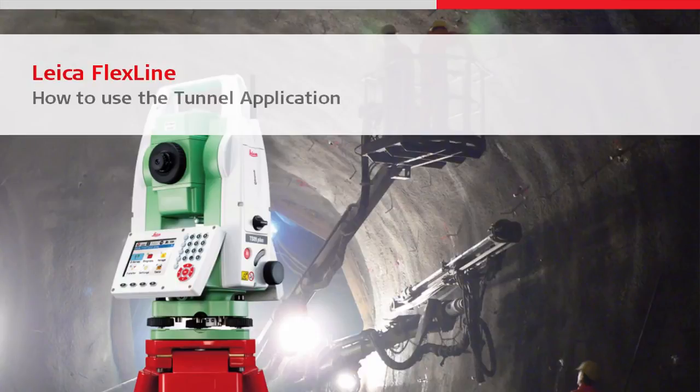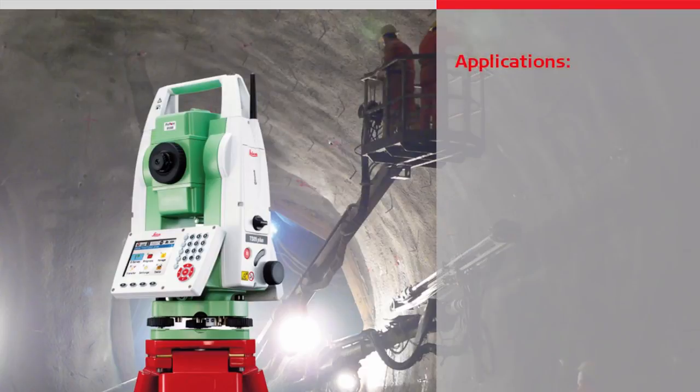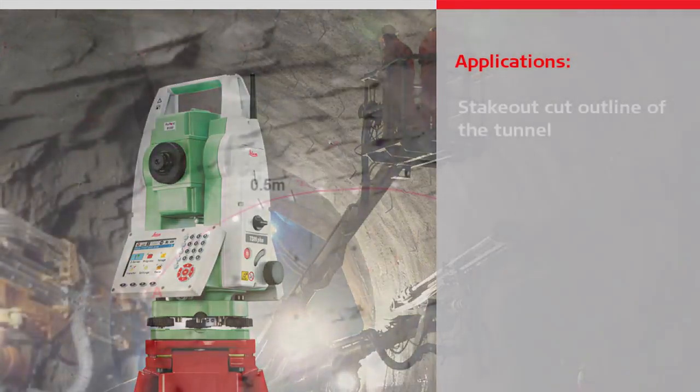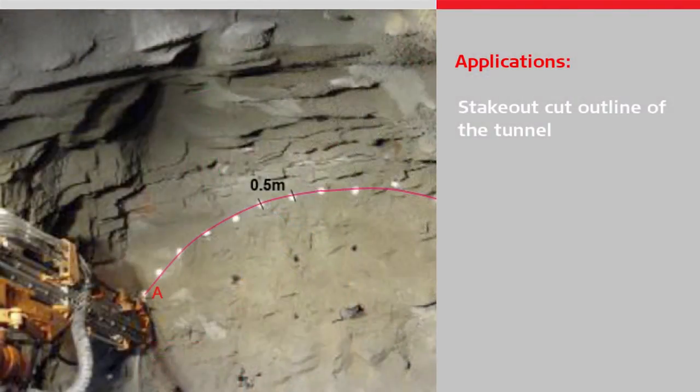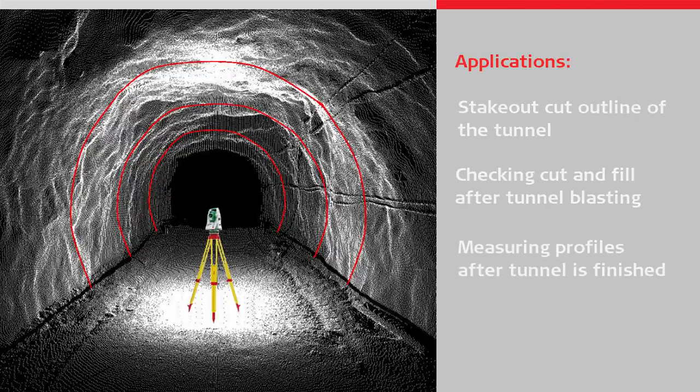This video will give an overview of the tunnel application available on Leica Geosystem's FlexLine total stations. The tunnel app offers a wide range of applications such as staking out the cut outline of the tunnel, checking cut and fill after tunnel blasting, measuring profiles after the tunnel is finished.